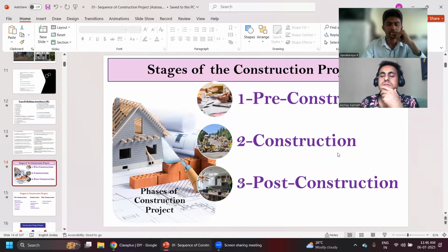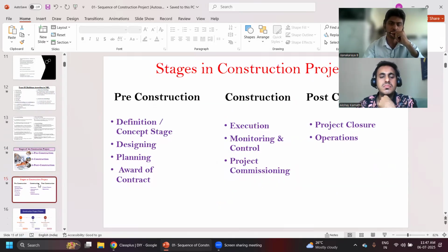Sir, in pre-construction, the client will come and say, I want this, and the engineer briefs that. Architectural plans will be done. From the architectural plan, we prepare estimates, the cost of construction. From the estimation we get the administrative approval, like BBMP. From the approval, we will do soil testing. If it is an apartment construction or a high-rise building, we will do soil testing and surveying.